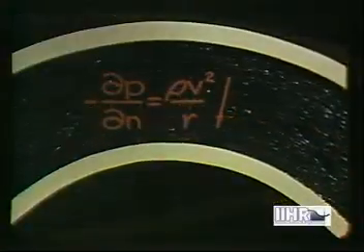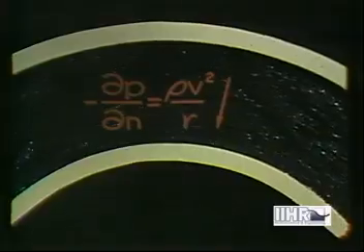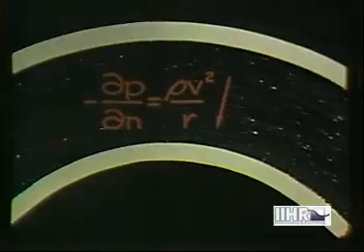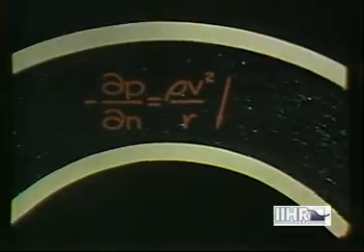Likewise, in steady, non-uniform flow, a tangential pressure decrease will accompany an increase in velocity along each streamline. And a normal pressure decrease will accompany streamline curvature in that direction. We shall discuss a few cases of unsteady motion at a later time.